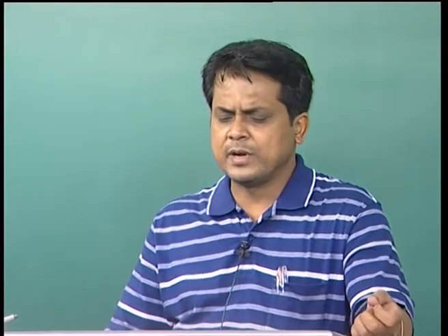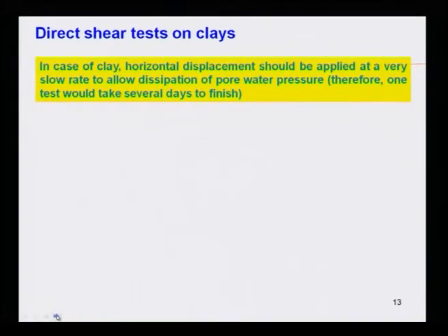So, this horizontal displacement in case of clay should be at a very slow rate to allow dissipation of pore water pressure. Therefore, one test would take several days to finish. That means it should be so slow, so that slow dissipation of pore water pressure will occur. So, one test would take several days to finish.